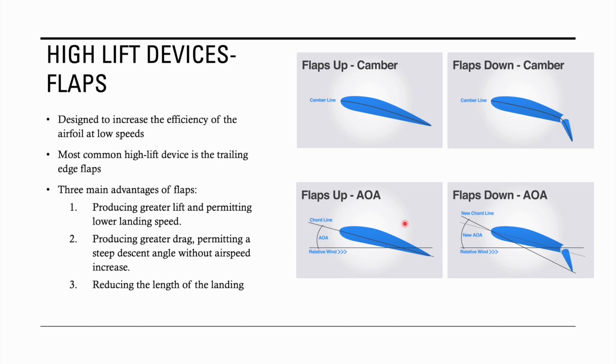So we'll primarily use flaps for landings in a small aircraft. There are a few specific types of landings where you'll go up to using 10 degrees of flaps for takeoff. Any more than that, these engines really don't have enough horsepower to overcome full flaps.